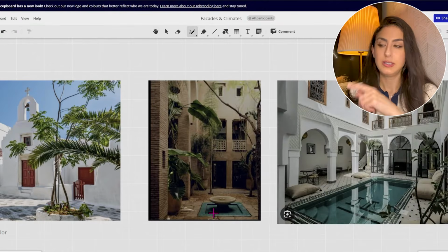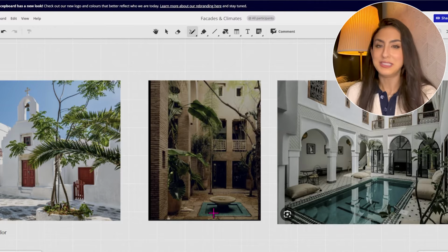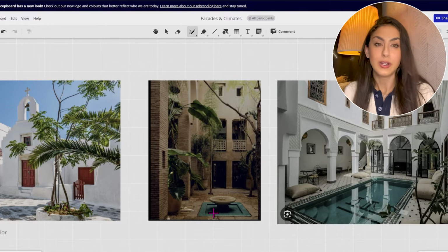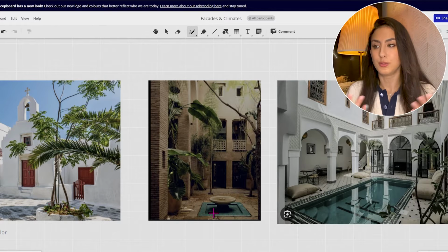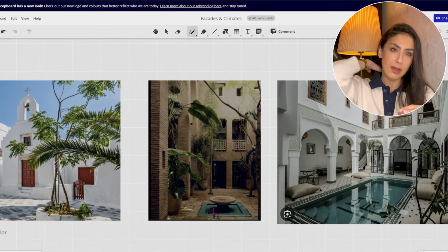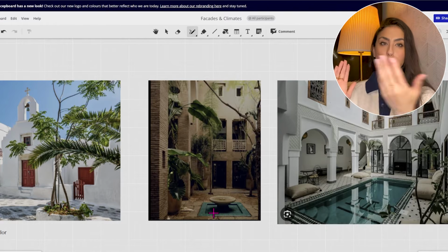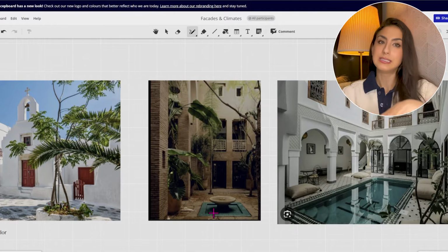Also courtyards. Actually, this is something that we have in Morocco, and I was born and raised in Morocco until 17, and I didn't know that courtyards serve a climate purpose. I always thought it was more of a cultural thing, which it is, but I think the main thing is because when you have a hot arid climate, you don't want to open up a lot of windows to the outside, but you want it to open up to the inside, because you have 4 walls creating all this shadow inside that courtyard, and that courtyard tends to be so cool during the day, and you're not getting a lot of heat from the outside walls, and all your windows are getting light from that courtyard.